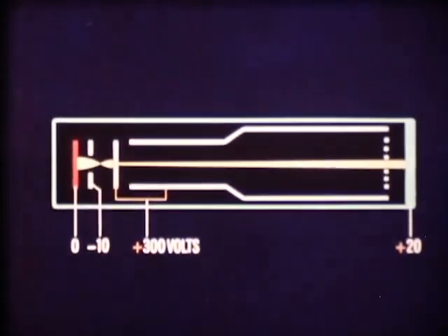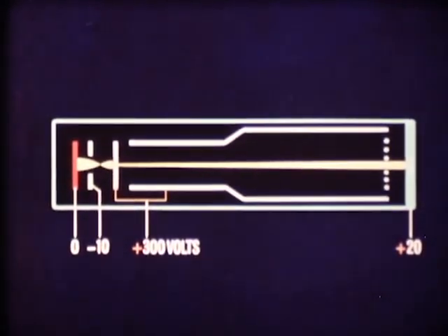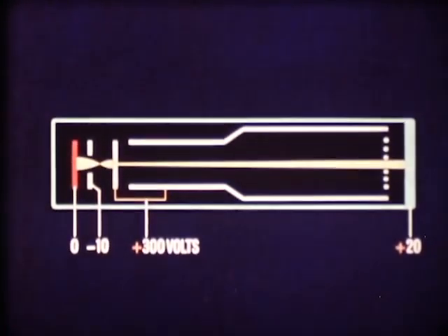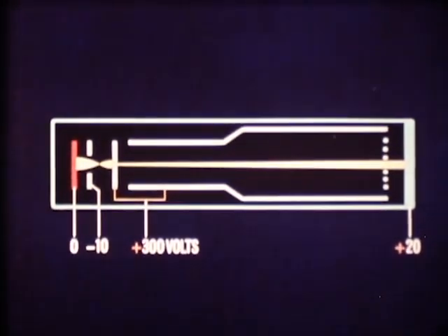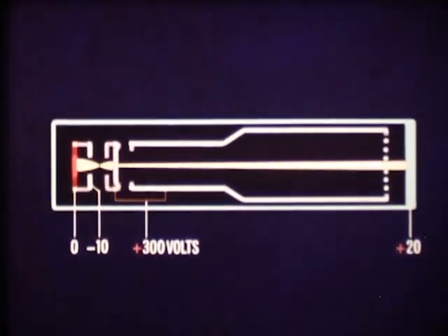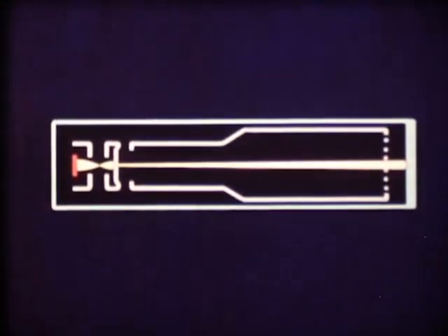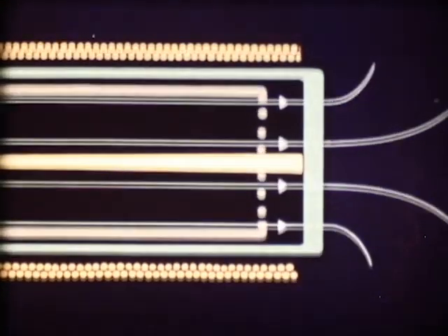In contrast to the anode system, the voltage applied to the signal plate is low, and this causes the electrons to decelerate and to strike the plate with a very low velocity. For practical reasons, the shape of the electrode system is somewhat modified. Although the electron beam is principally a thin, parallel stream of electrons, some spreading does in fact occur. Consequently, it is too wide to satisfactorily scan the small picture details, but it can be focused by a magnetic field.